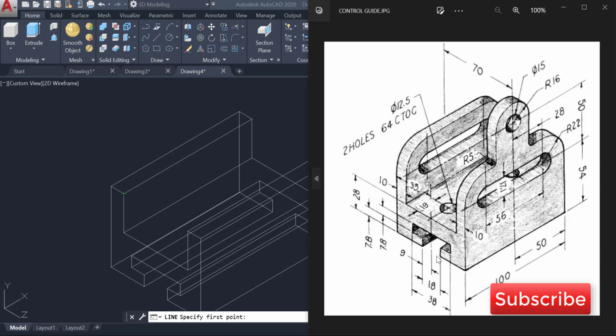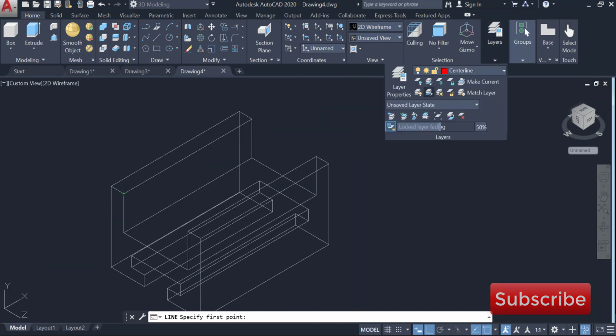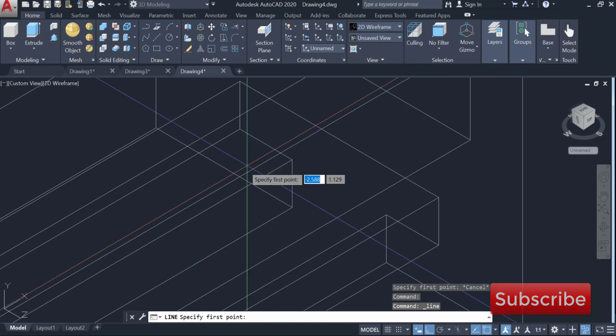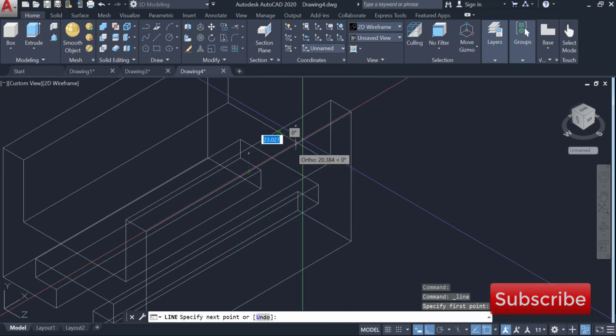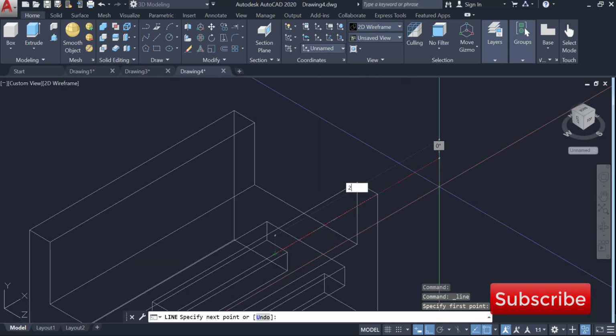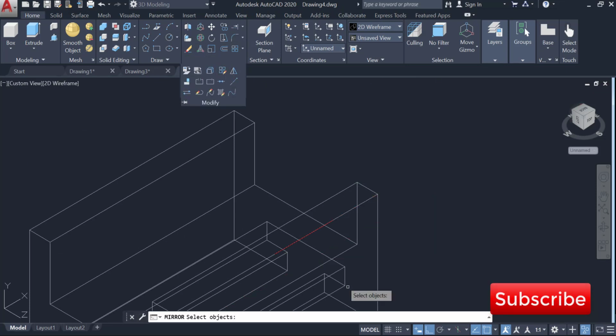So our drawing is this one. We need to draw what I did. Yes, this line. Let's make it a layer red. Draw a line of 28. Make sure that you touch the correct line. Touch this one. Okay, so pull it, make it 28, and then we can mirror it so that it can be on both sides. Click mirror, select the line.